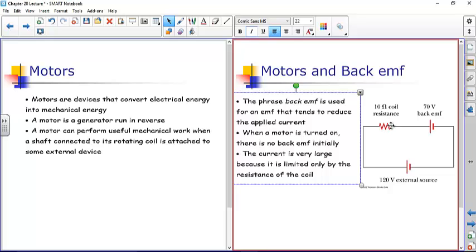And there's a self-compensating situation where the motor, as it spins, is also generating voltage as a generator, and that generator develops a voltage opposite the direction that you're applying it with the battery. And so you only have a net amount of voltage that's available to push the current through the motor. And you'll reach some place where the current through the motor is just providing enough torque to keep the motor running and overcoming friction, but it doesn't have any additional current to give you torque to make it move any faster. So you kind of reach this steady state condition.